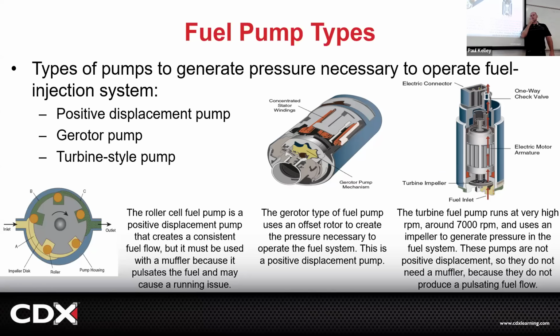You want the good news? They come together. You're not going to say, let me get the fuel pump motor and put the wet end pump part on the new motor. You're doing both. They come together. All you have to verify is that the fuel pump is getting the voltage it should get, and is it making the pressure it should make?